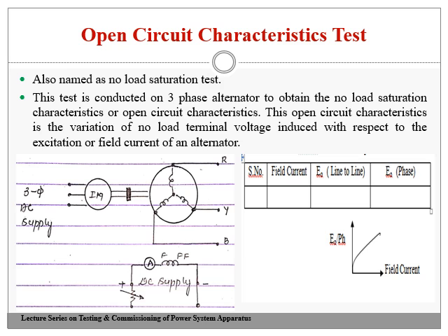Afterwards we tabulate it and obtain the phase values of the no load induced voltage. We call it the no load terminal voltage induced across the stator terminals when the alternator is under no load condition. Then the phase voltage is determined.